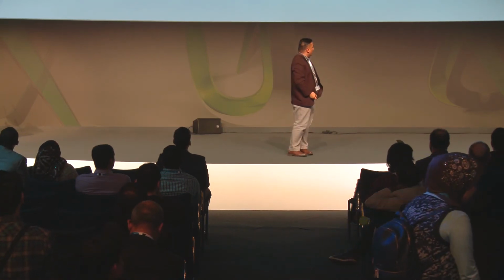Okay, when we talk about management standards, because of the time constraint, I will talk about the BIM Execution Plan and the Common Data Environment. Do you know that there are two variations of the BIM Execution Plan? Have you heard of the two variations, or have you only heard of a single generic BEP? All right? So in our practice, let me talk about the BIM Execution Plan, or the BEP, first. We have two variations of the BEP. These are the pre-contract BEP and the post-contract BEP.